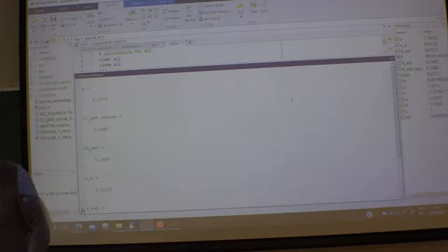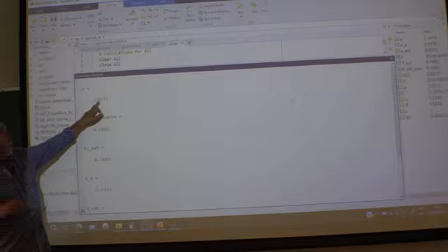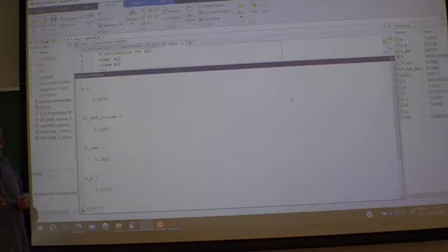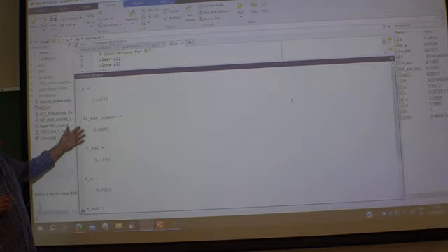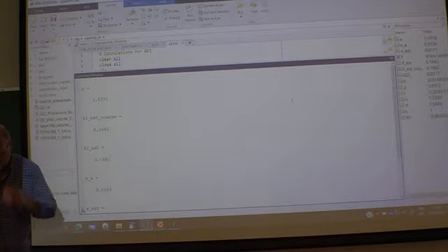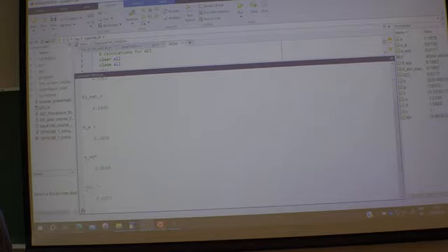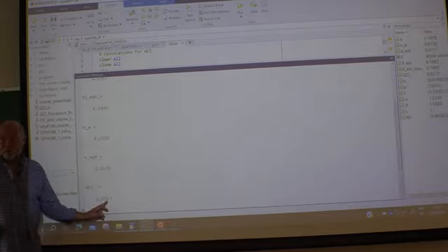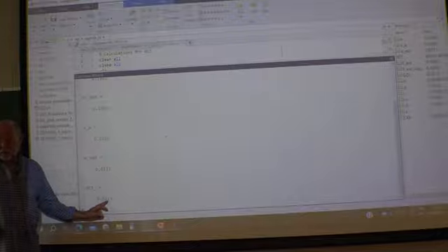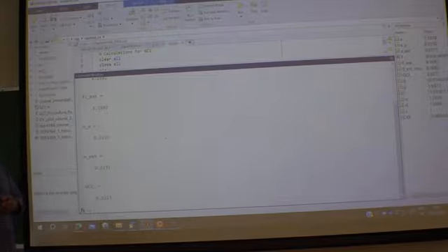So here then, you sort of have all the numbers you need. I got a P, same as they got in the article. You have the extrapolated values, the error estimates, and finally down here now, the GCI, 2.2% of my monitor value.